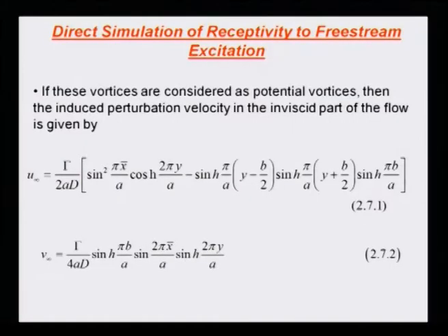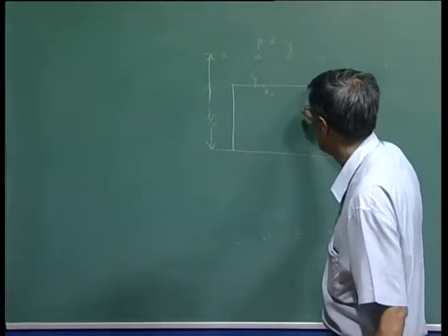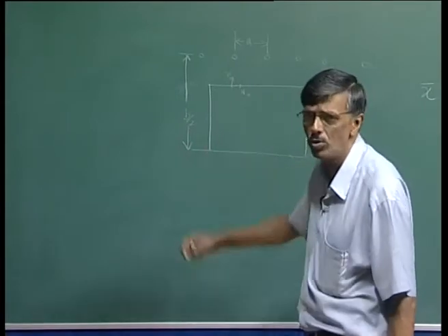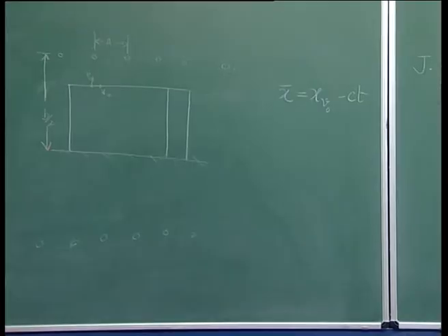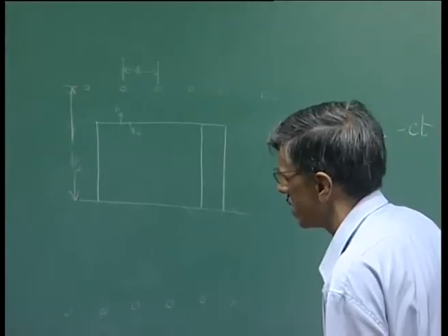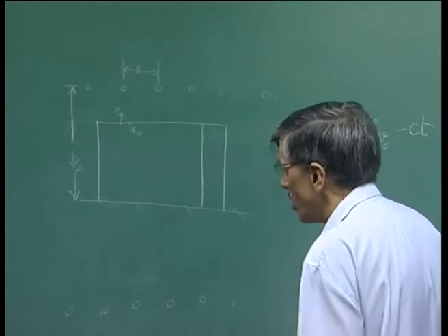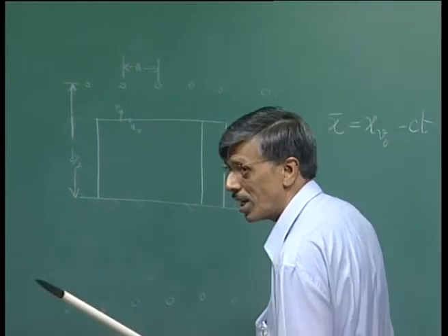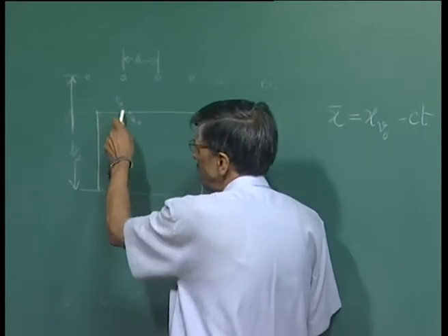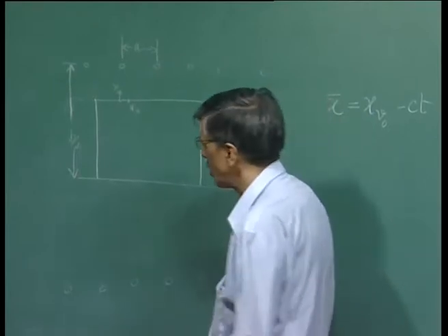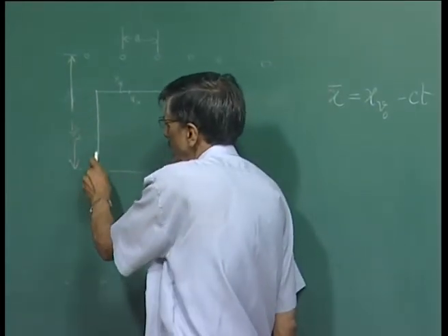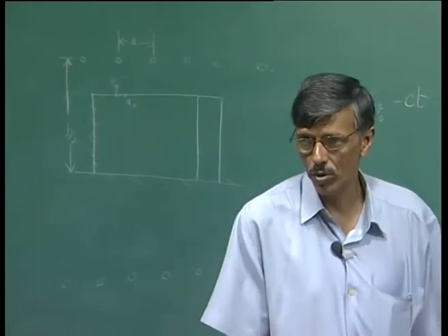So wherever you position the computational domain, you know the x and y, plug in those quantities and you should be able to calculate the induced velocities at the box periphery. So that's quite easily done. So you realize also that there are two things. It's not only that u infinity, v infinity is imposed on the top lid of the computational domain, you also get it happening on the inflow too, right?